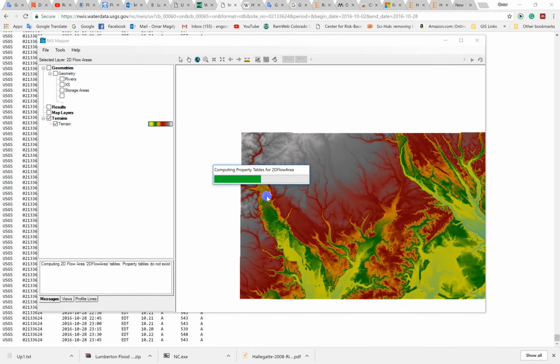And I can ask a question here. So I want to know whether HEC-RAS considers the land cover or not. What is the land cover? For example, the houses? Yeah, houses, and whether it is forest there or building. Actually, it's a digital elevation map oriented, not shapefile oriented. Okay. So everything in your digital elevation map should be mapped on it.